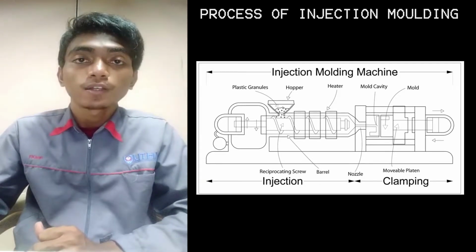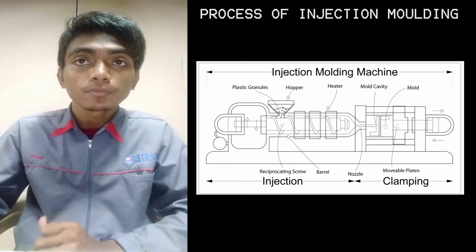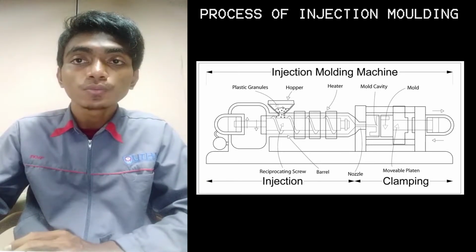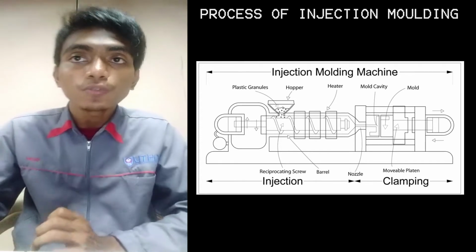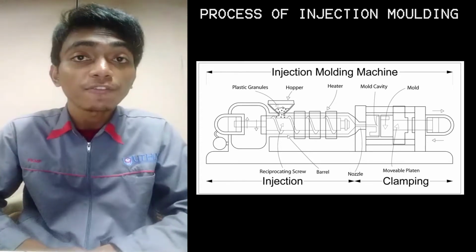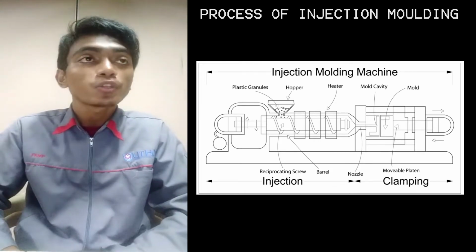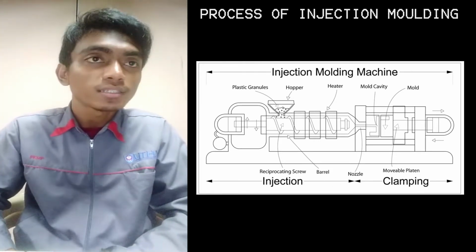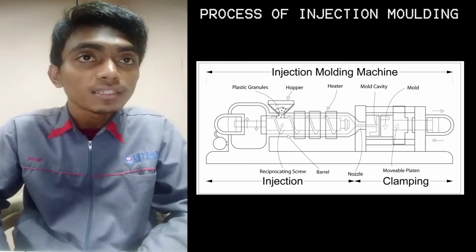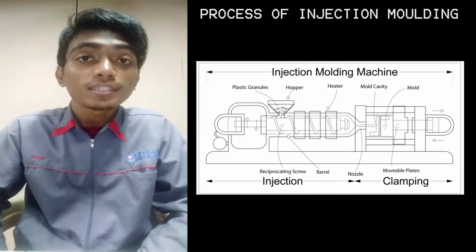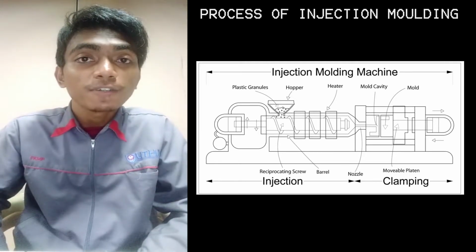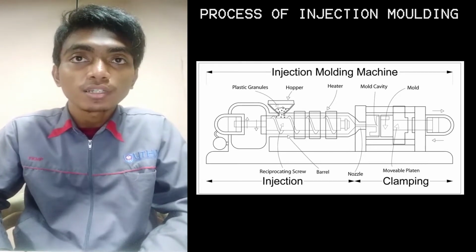The material enters the groove of the screw from the hopper and it's advanced toward the mold as the screw rotates. While it is advanced, the material is heated, melted by pressure, friction, and additional heaters that surround the reciprocating screw.